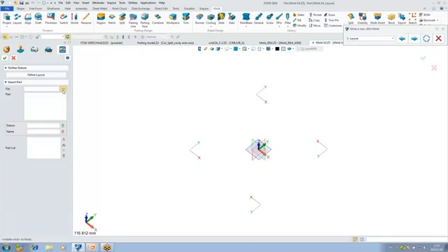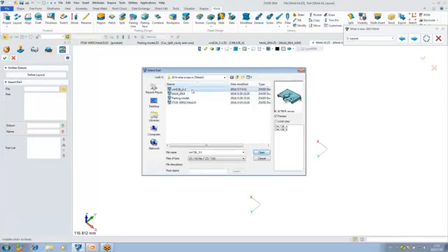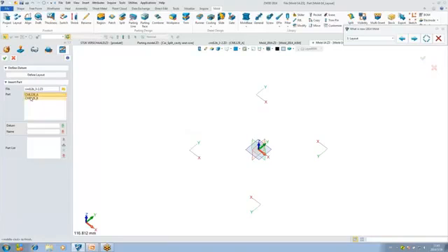Next we will select the product model. Okay, this one. And you can see the list, the object from the part list. There are 2 products here. Just middle click or directly go to the datum input field. Here we can select the datum plane. Okay, I will show you the multi-cavity mode firstly, how to do it in the new ZW3D version.